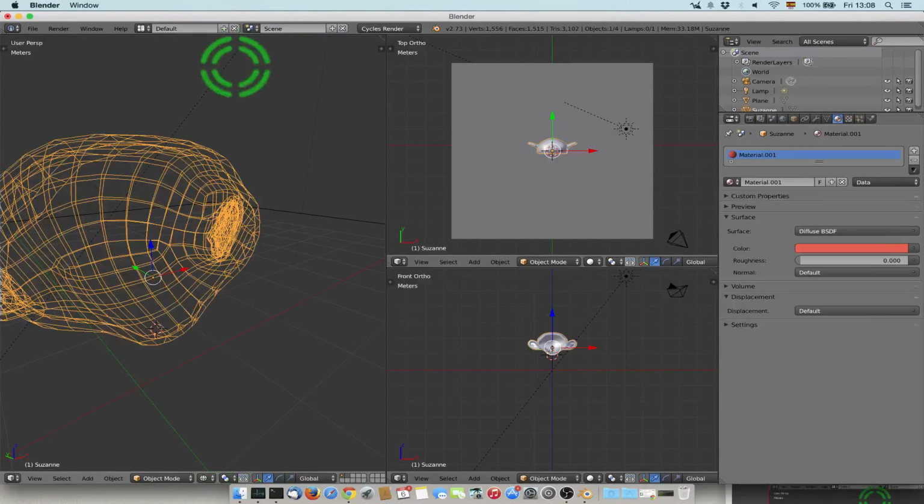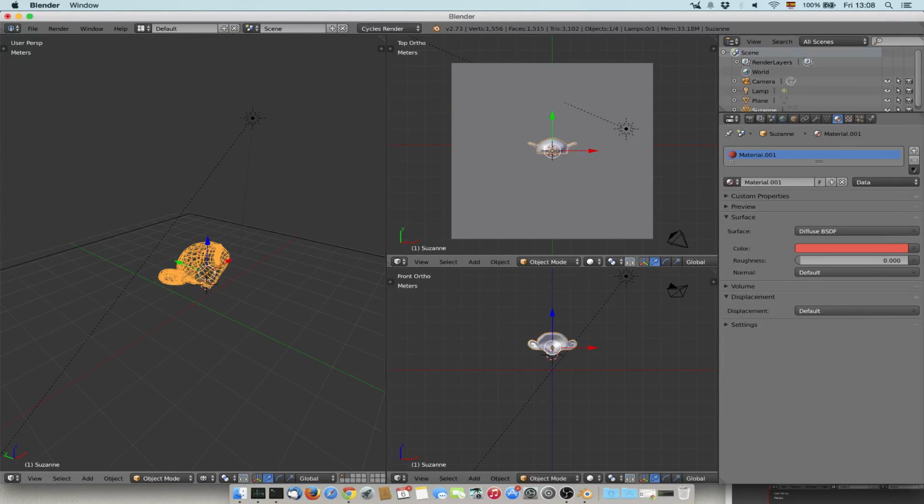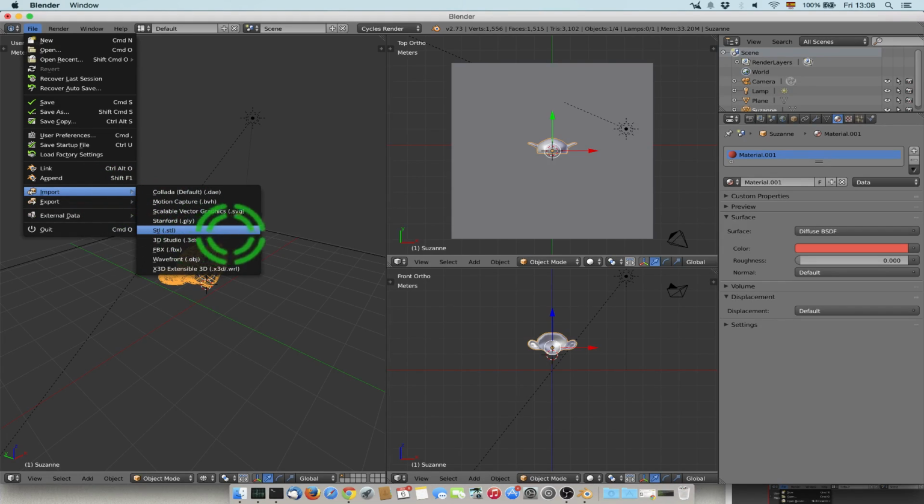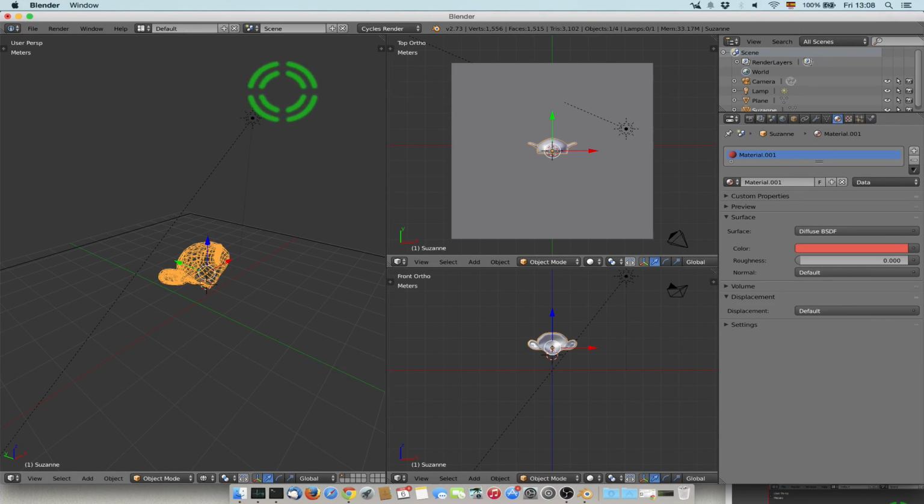So now what do you want to do with this? A very interesting thing is doing File, Export, the selected as STL, and then the STL can be embedded, can be 3D printed, and so on. You can also do Import STL. You can do Import SVG. We will see it later. So you can import the 2D drawing and then transform it into 3D here. Okay. So that's the basics of Blender. You can do even more. You can do texture, animation, video editing, but that's not what we need at the moment.